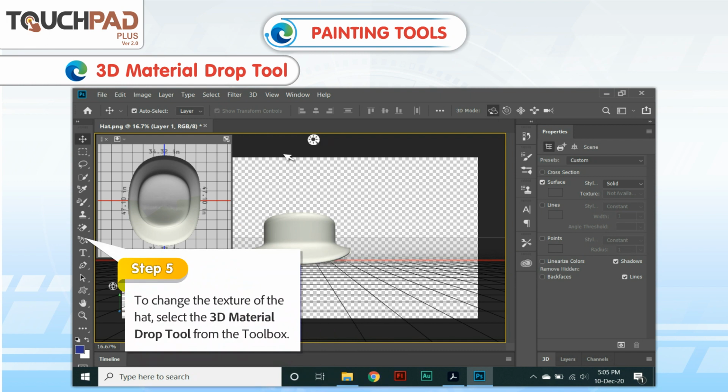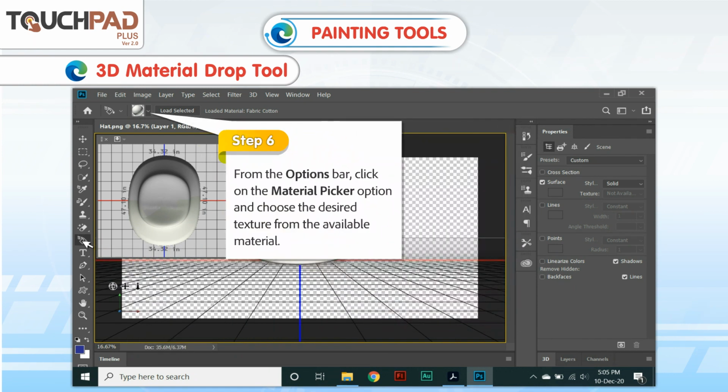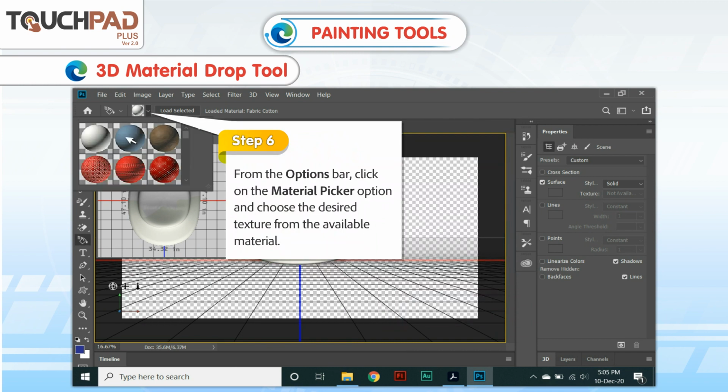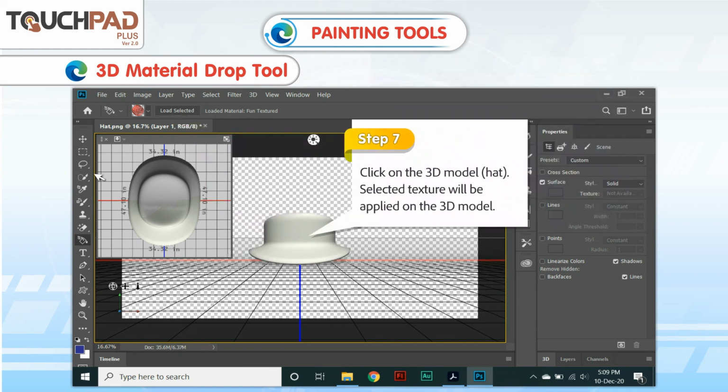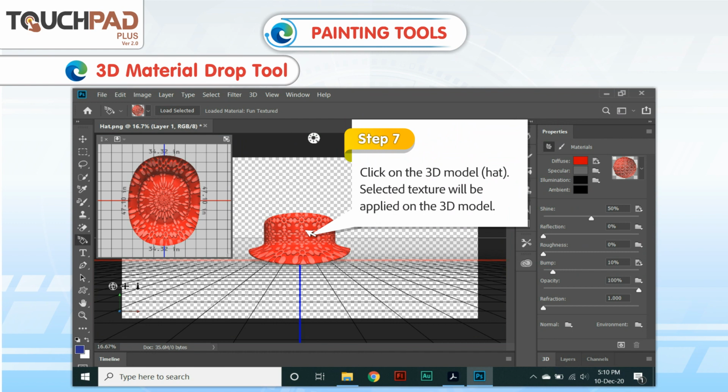Step 5. To change the texture of the hat, select the 3D Material Drop tool from the toolbox. Step 6. From the options bar, click on the Material Picker option and choose the desired texture from the available material. Step 7. Click on the 3D model, hat. Selected texture will be applied on the 3D model.